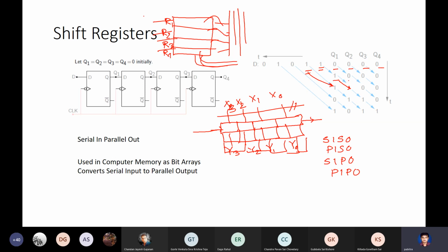You have a set of control lines. So this vector of bits is called a bus. For example, here you are writing the data input and output. It's called a data bus. And here you are choosing which register to access. This you call an address bus.